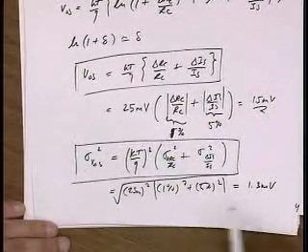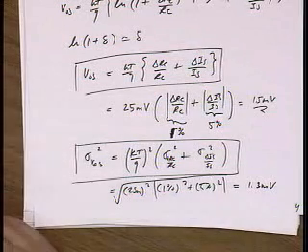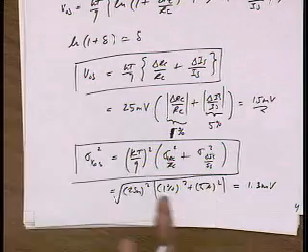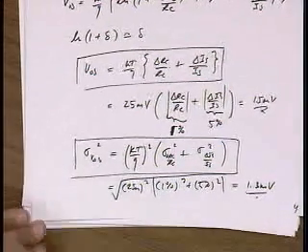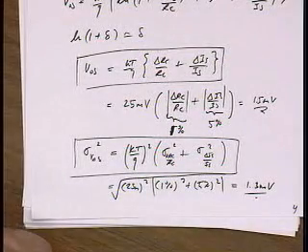So that's interesting. That tells me that the offset voltage is going to vary on the order of a millivolt as I look from part to part. So most of the parts will have an offset voltage within this bound of the DC value, of the mean value.